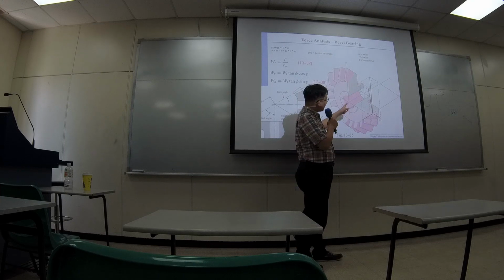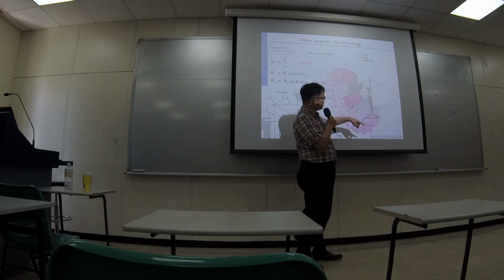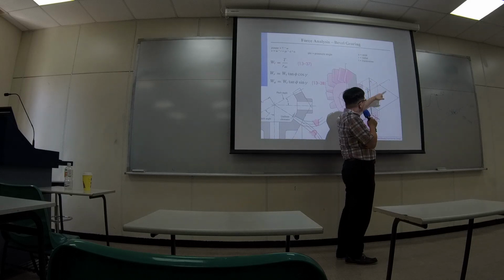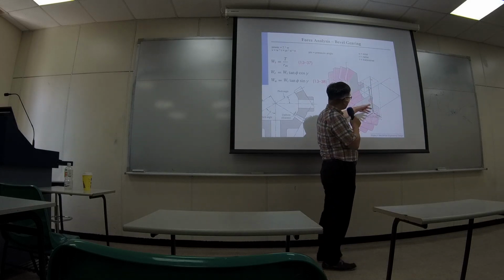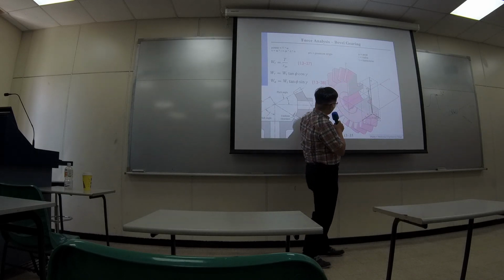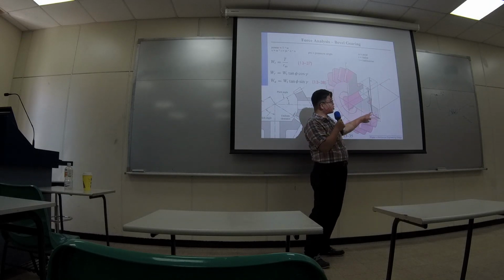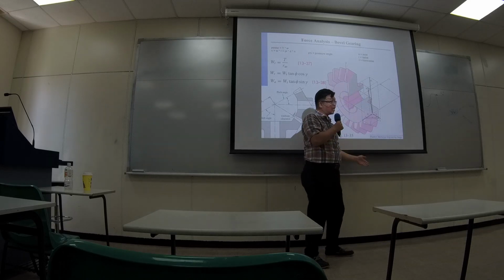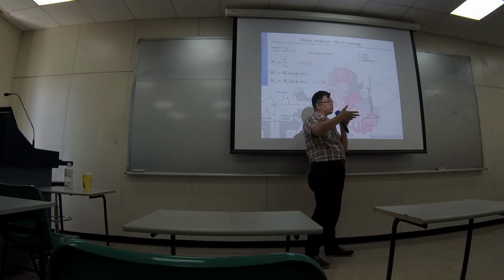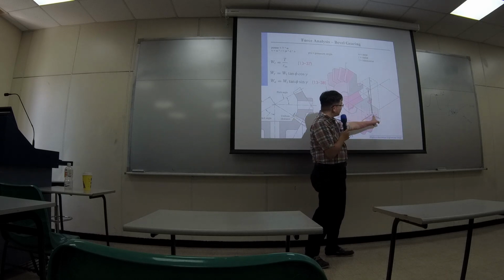They label those 3 components as WT, which represents the transverse direction. So how come it's the transverse one? Because if you observe this as a pitch circle, then this is the tangent direction. So they treat that tangent direction as the transverse direction.